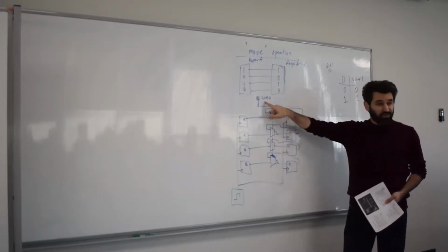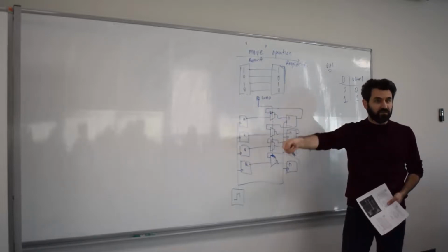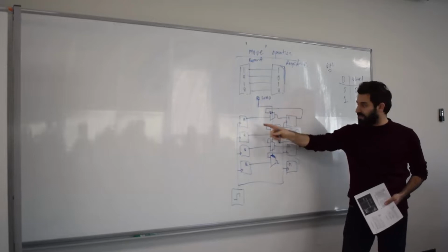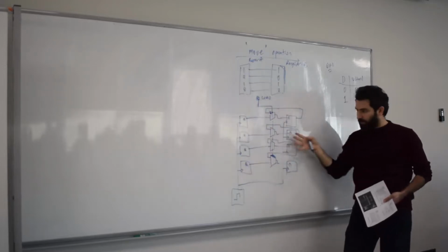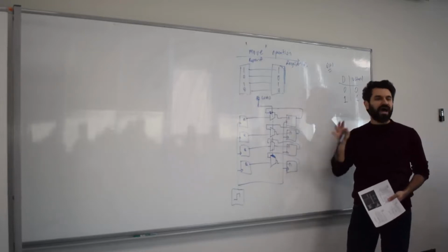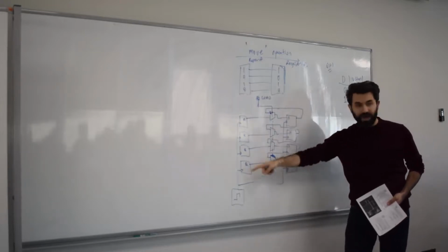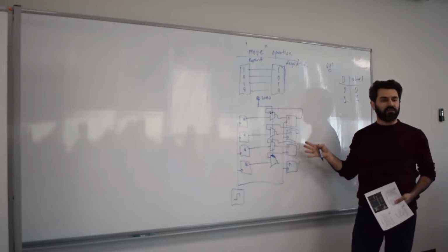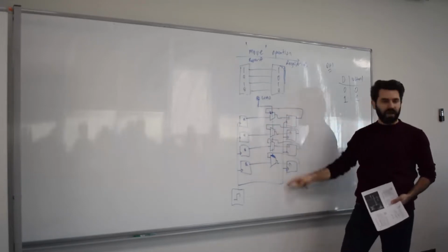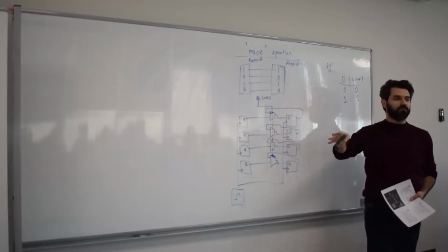But whenever you want to store something new, that is the write command that you give to the register. When load is 1, that means these new values will now be sent in parallel to these D flip-flops, and those D flip-flops will now assume these values as the new state. Then you turn load to 0 again, and you can store the new value for as long as you want.